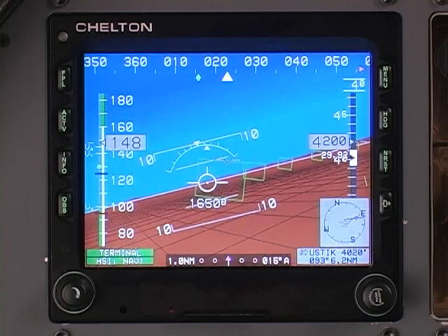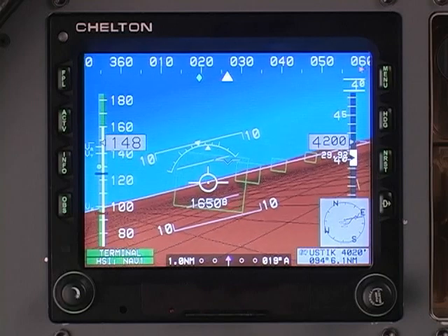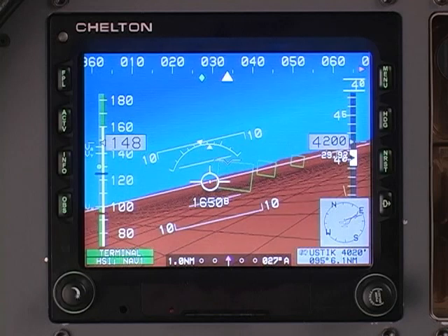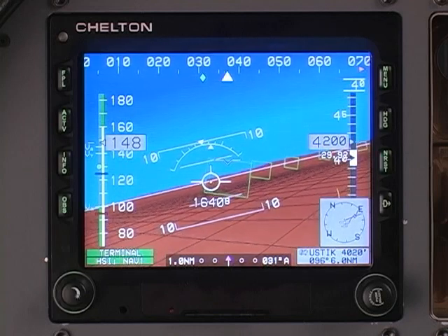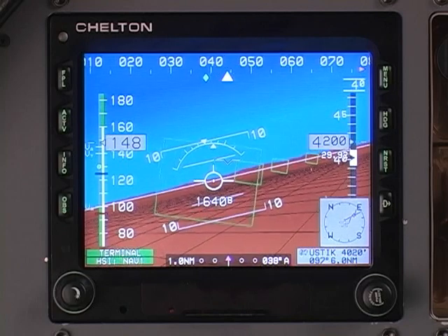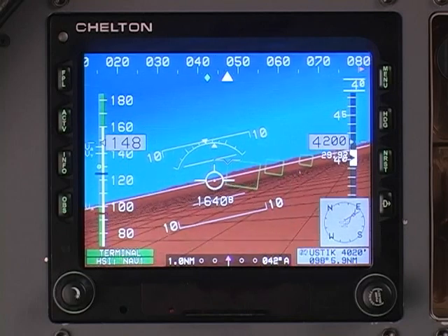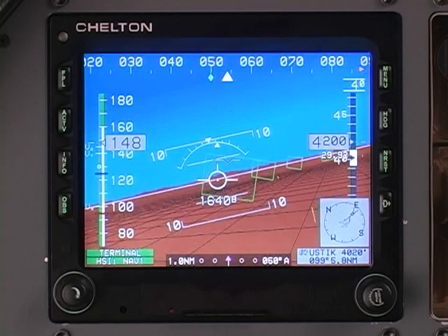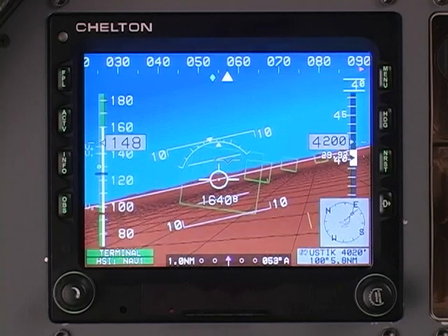Flying the Skyway is like driving down the road in your car. You see a turn coming and you turn with the road when it turns. On straight sections, you make tiny corrections with the steering wheel to stay in your lane. Fly the Skyway the same way, but don't worry if you drift outside of it, especially in turns. Remember, it is half the width of the localizer just prior to the runway.